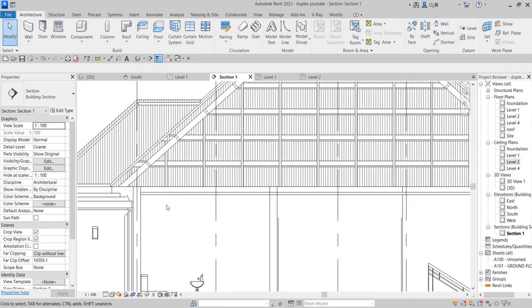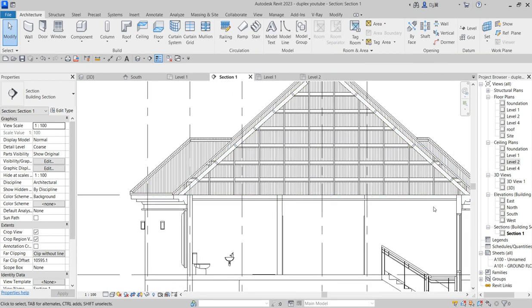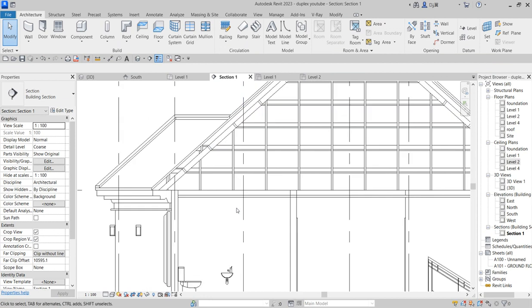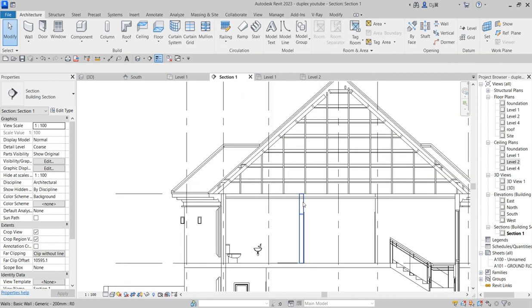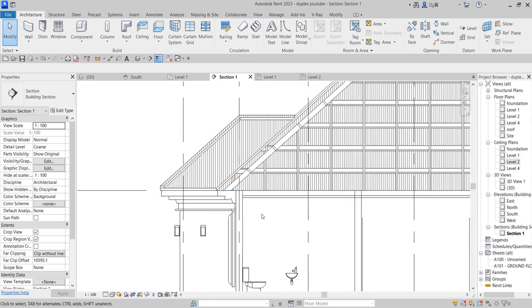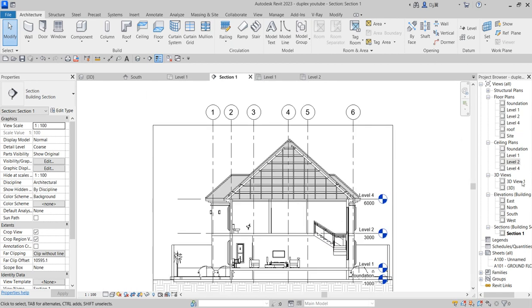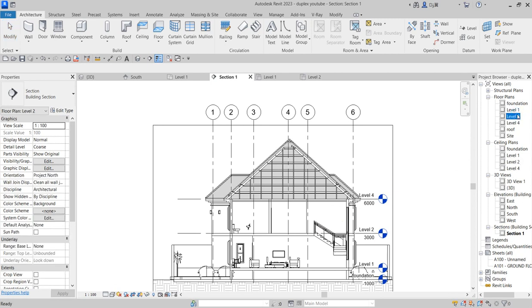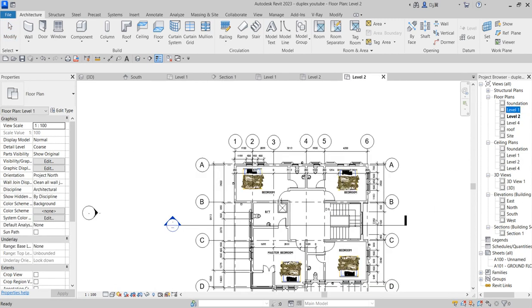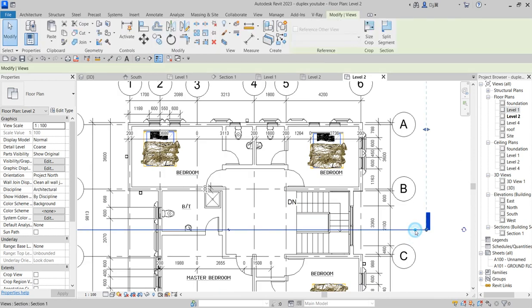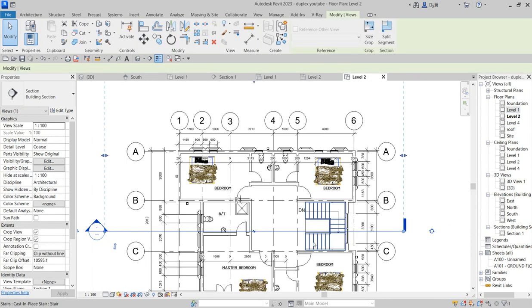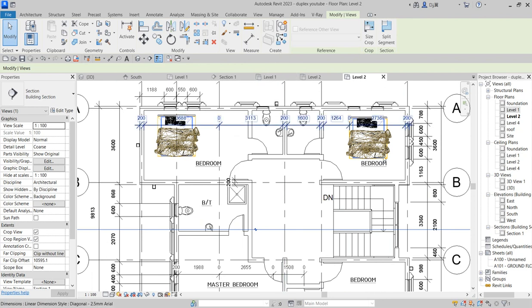So now if you want to bring your lighting, if you want to do interior later on, you can bring your lighting and attach it to any part of the ceiling positions. So now it's going to give you a headache. So let's adjust something in this section by going to level 2 or level 1. And what I want to adjust is this. You can split this section into 2 by bringing parts. So like let's say split segments. So split this. Can you see?